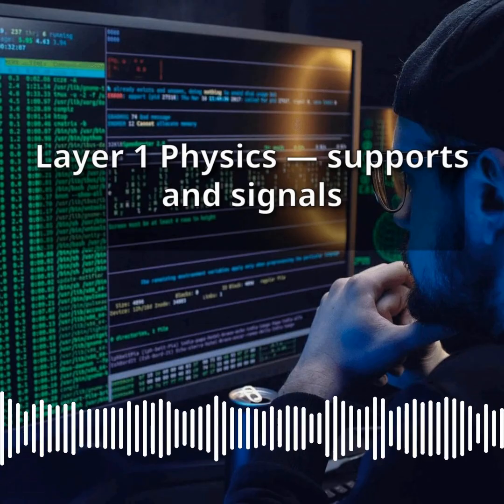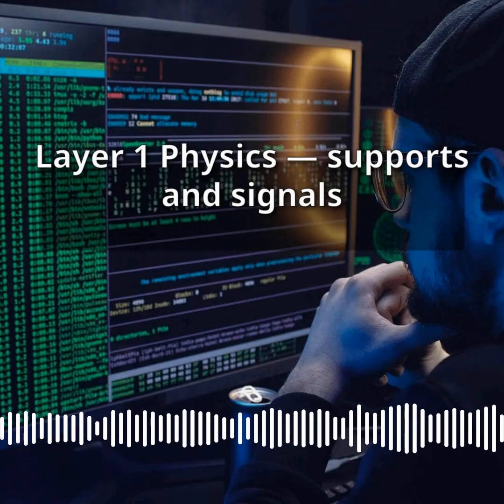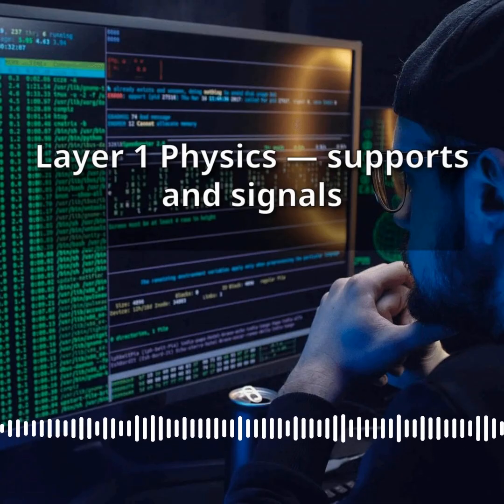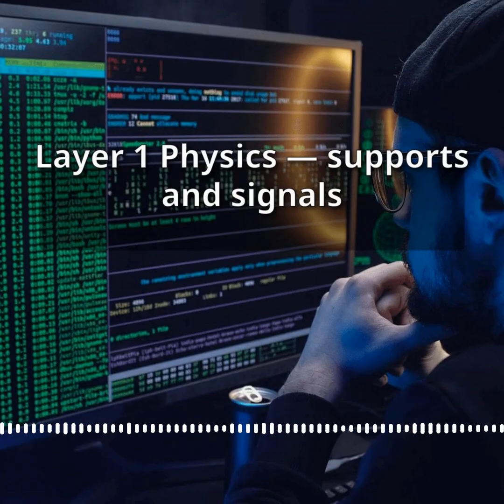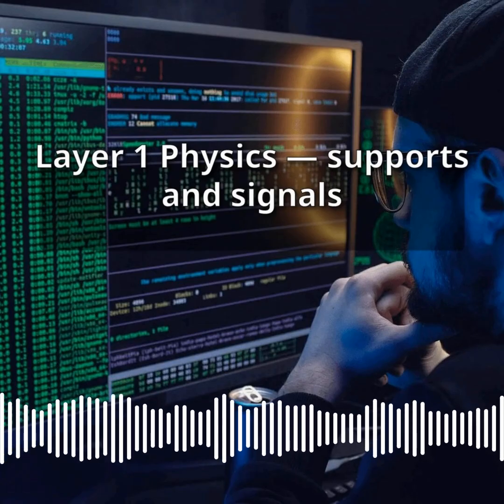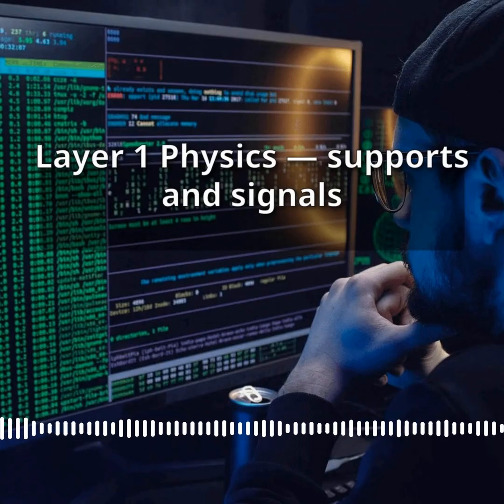Multi-mode fiber has a wider core, typically 50 or 62.5 micrometers, that allows multiple paths of light to travel simultaneously. This is cheaper but limits the maximum distance, typically up to 550 meters at high speeds. Multi-mode fiber is commonly used inside buildings and data centers.